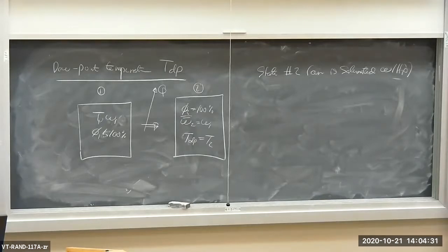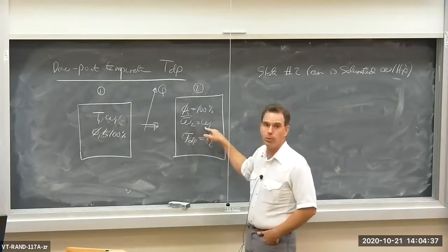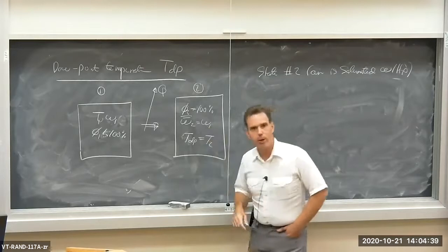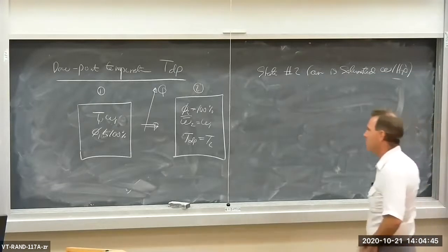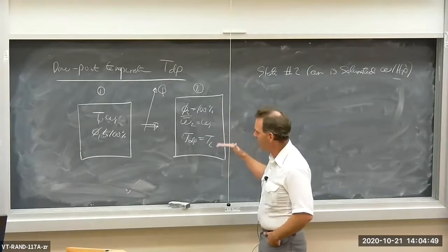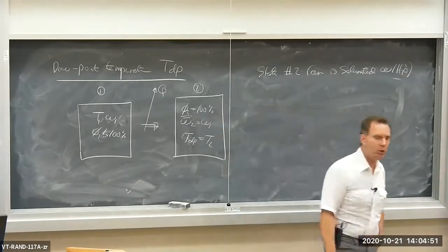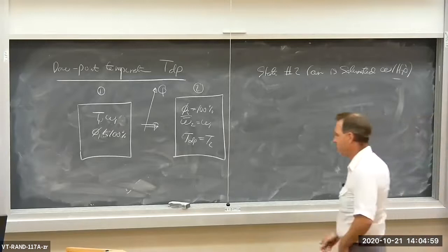I'm not adding any dry air. So omega is the same at state 2 as at state 1. That means the partial pressure of the H2O stays the same, because the amount of H2O in the mixture doesn't change, so its partial pressure remains constant. But the temperature is falling, so that means my saturation pressure for the H2O is also falling. So that's pushing up my relative humidity.